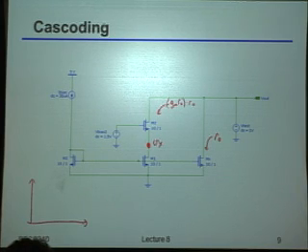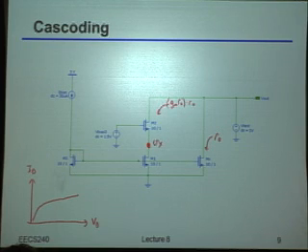If I take that bottom transistor and I plot its ID versus VD, then there's no magic. In the case on the right, if there's a certain swing in the drain voltage, as an example, let's say plus minus 100 millivolts, that's going to translate into a certain swing on the drain current. In other words, you're just riding on the slope of that particular device.